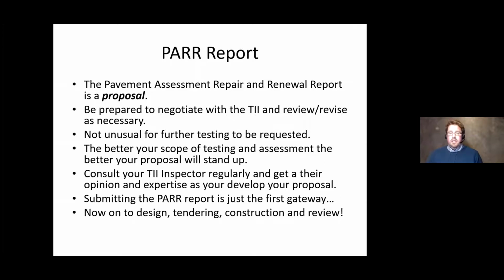And that's why it's critical to get familiar with the site first, so that you know where you need to test, how much testing you need to get done, and that if you need a greater intensity of FWD testing along this stretch, go get it done. Better to get it done at the start as opposed to have the TII tell you that you need to get more testing done, or more cores done or more slit trenches done just to get to the bottom of the pavement. Do it first, build up your case profile and be sure of it.